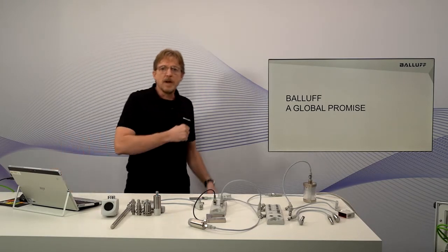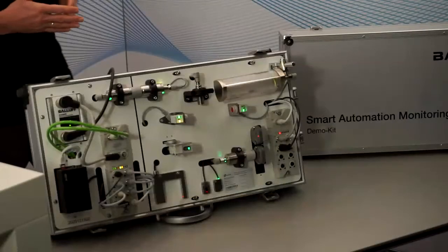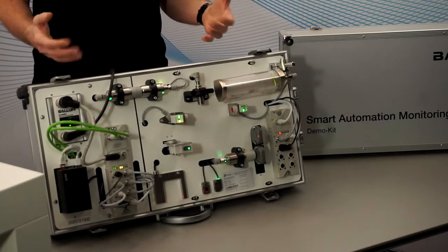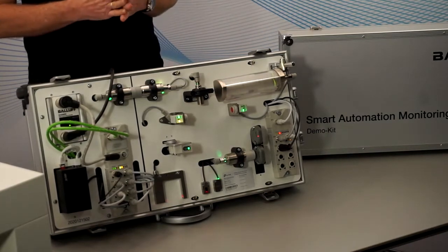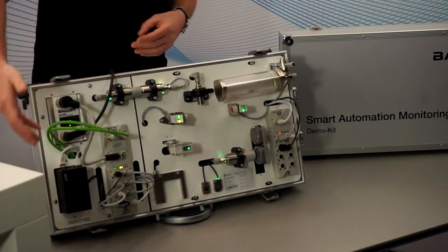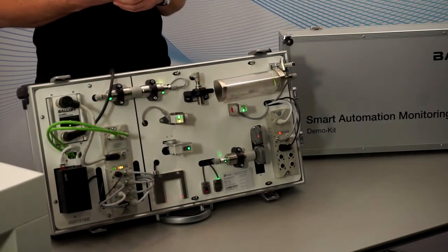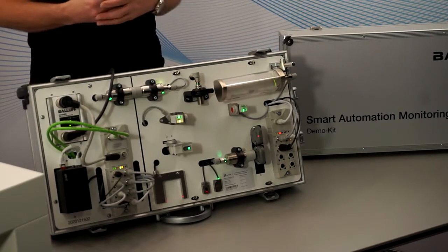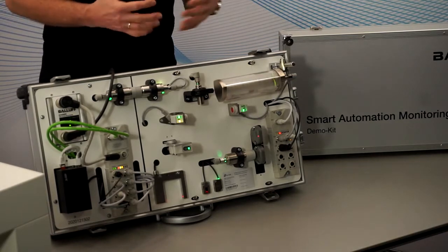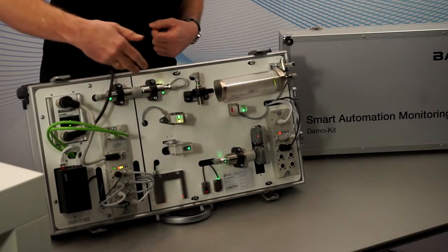For this, first, I would like to introduce you to our demo case. In this demo case, we created a small topology of how it could look in your application. We have the PLC controller, which is here a Raspberry Pi, and connected to this via a network we have the backbone, let me say, of our system, which is the IO-Link master module. Everything is based on IO-Link technology, so every single component comes with an IO-Link interface. Connected to this master are the different components.